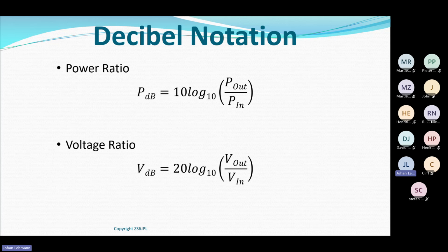Power is not a singular value. What's the formula for power? If we go back to our textbooks, power is the voltage times the current. There's two things I have to multiply with each other to get power. So I use only 10 log that ratio. So that's an easy way to try and remember it. If you see voltage or current in your exam paper, to work out the decibel value for a voltage ratio or a current ratio, just think of your triangular Ohm's law. You can't break voltage, current, and resistance down further. But power is two values multiplied to each other. So I hope that helps you to remember when to use 10 log and when to use 20 log.